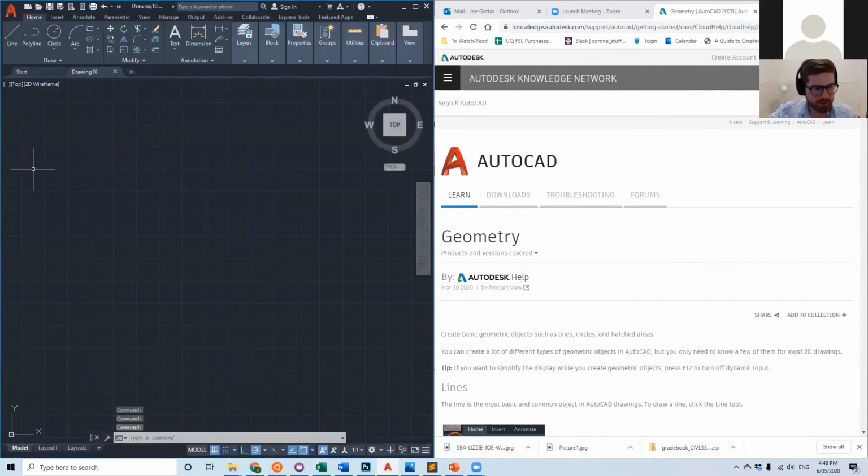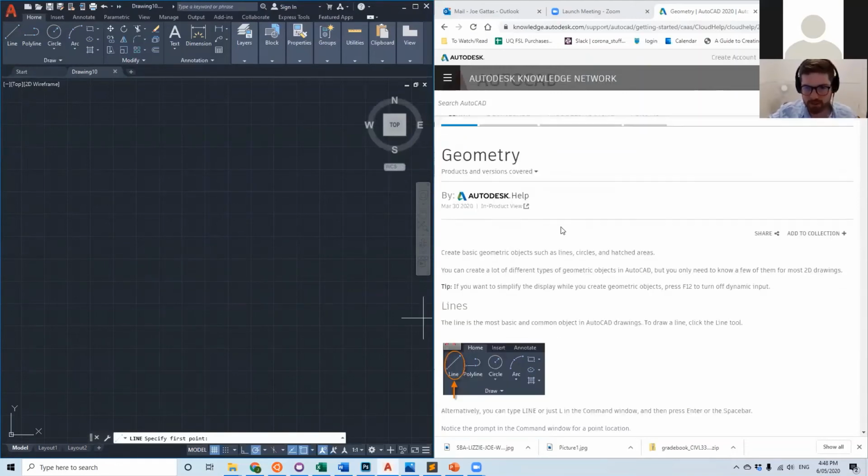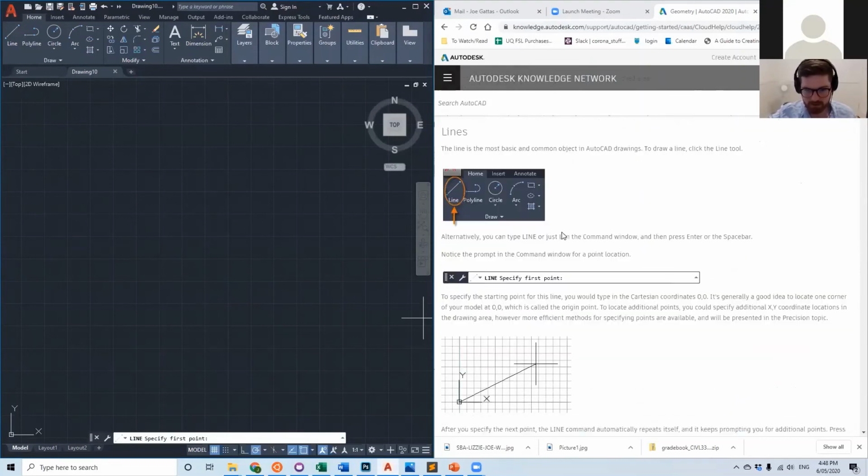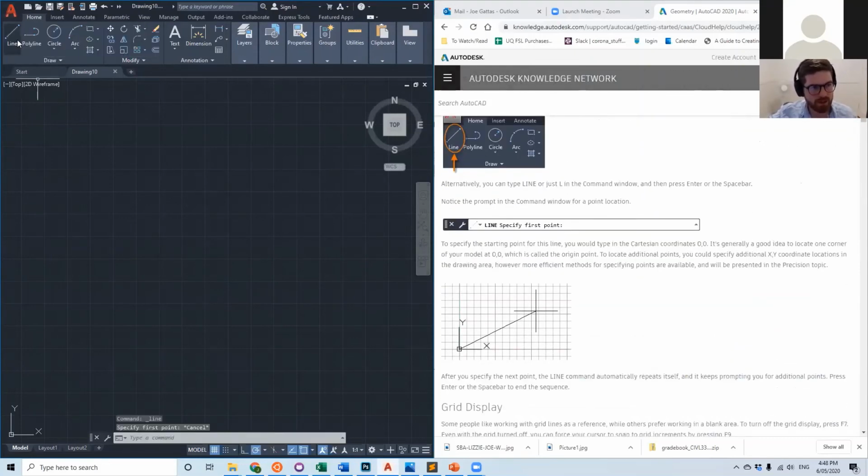And I don't say that in a condescending way at all. I would honestly just start drawing in 2 dimensions. If you're new to CAD, it's great. And you're going to pick up a lot of the basics pretty well. So these are about in order of use. Line: click, click, enter when you're done. Circle: click, click, you're done.